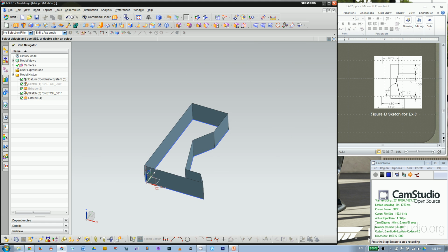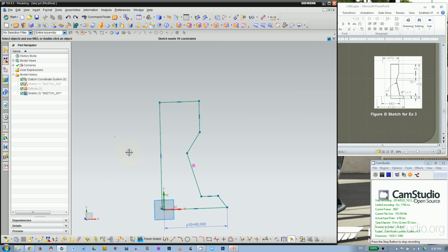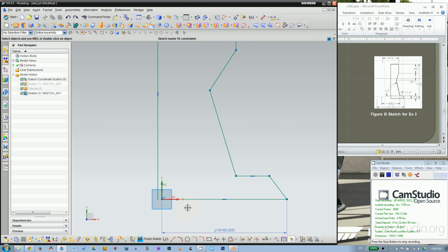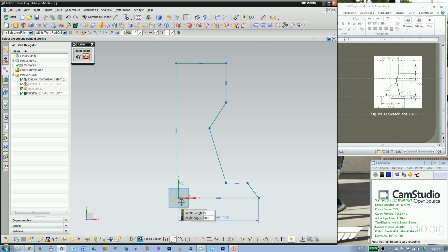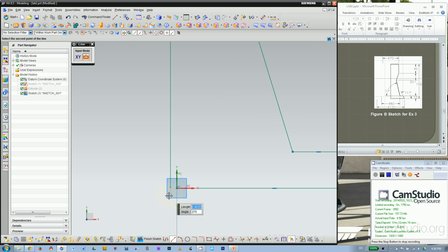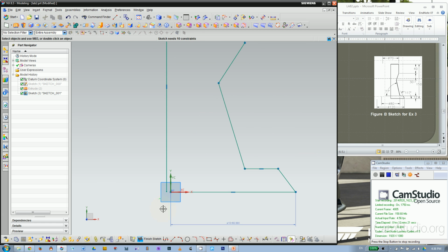And also, then probably you found this place. You say, okay, I'm gonna close this, right? I'm gonna use a line instead of quick extend, which is recommended, or which is a better way. I'm gonna use this straight line to close here, and without snapping to this point, you just sloppily drop this line here, close this.